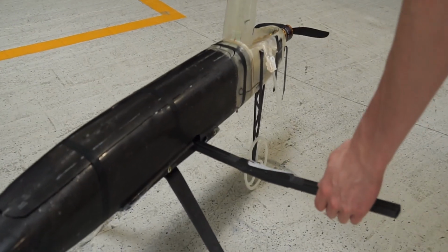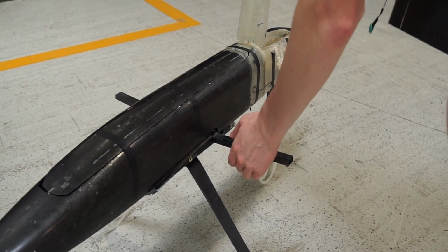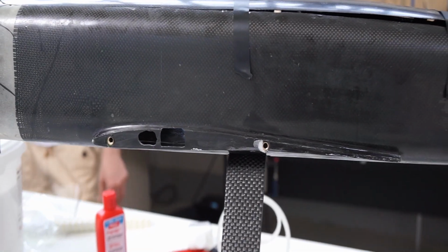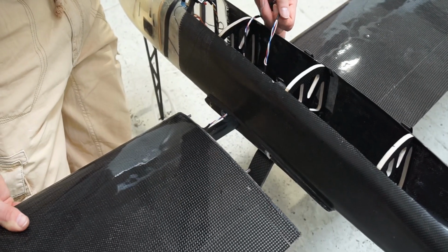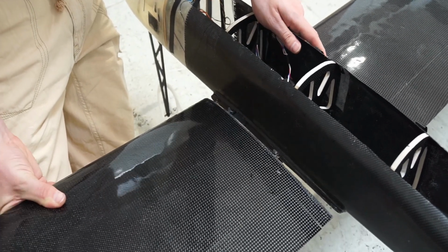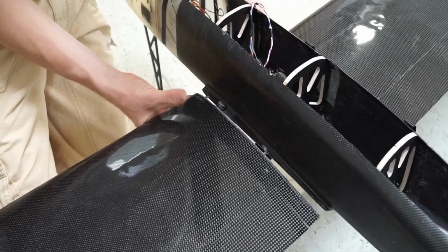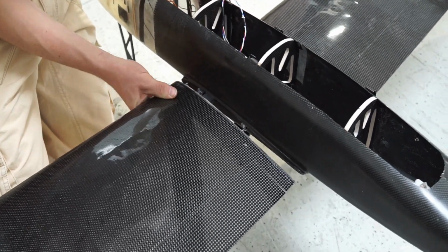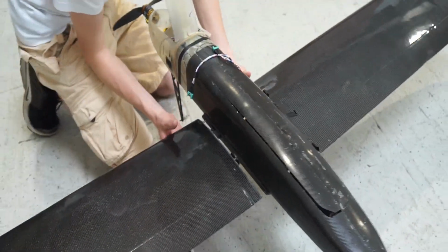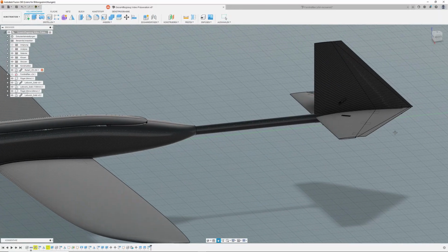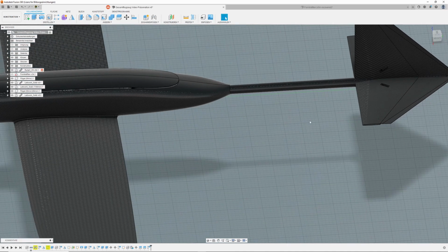The wings are connected to each other by a carbon fiber spar, which is made out of 2 10mm carbon fiber tubes and has a dihedral of 2 degrees. Its purpose is to resist the momentum load on the wing during flight. The fuselage is connected to the wing by 4 steel pins, which also transfer the lift force from the wing to the body. The main body of the fuselage does not extend all the way to the empennage.